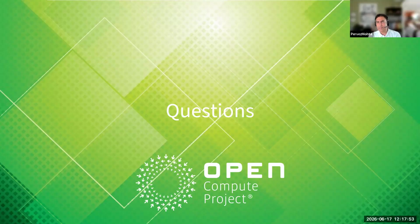One more quick follow-up before I jump in, Ahmad. You mentioned 10 megahertz primarily because of the telecom legacy inputs. But are you concerned at other frequencies that you are going to have minimum pulse width considerations with respect to edge detection, rise detection, and so on?